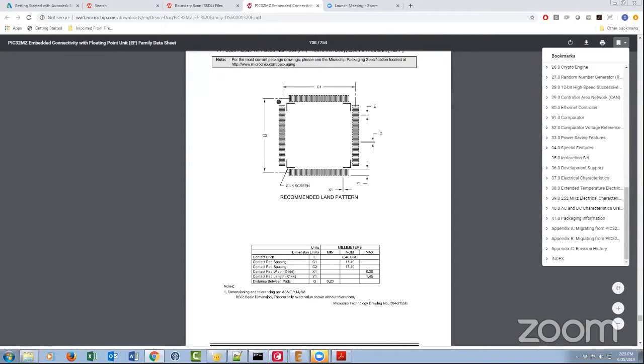So the width is going to be very slightly bigger than the thickness of the pin, because in order to leave 0.2 between them, you can have 0.1 on either side, and you already have 0.9 taken up by half of the pad width. So really, the Y value is just supposed to be 0.20.